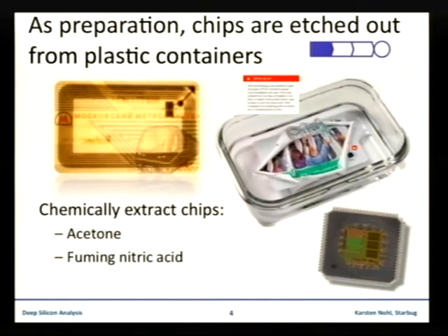But most of the times the chip is not completely bare there, but it's still encapsulated in epoxy. So there has to be another step before you can get the bare chip. And for this one you will need fuming nitric acid. It's a very bad acid, so normally you shouldn't do it in your kitchen, but send it away to a chemical laboratory or something like that.